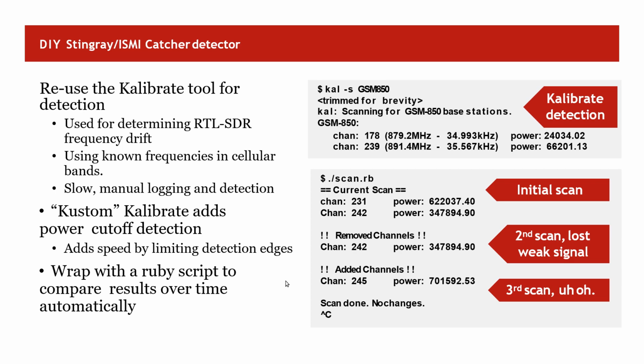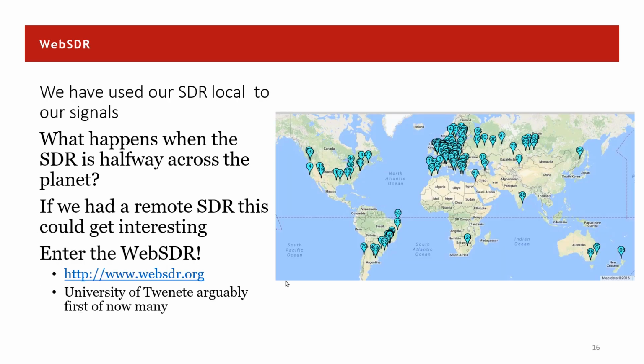You can get hands-on. There are a lot of web SDRs available free of cost, which you can search for on any search engine, and you can find many of them. And we have Multimon-NG and SDRuno for Windows for piping out to other decoders if decodings are there. If encodings are there, we can go with LSB, AM/FM, and all.